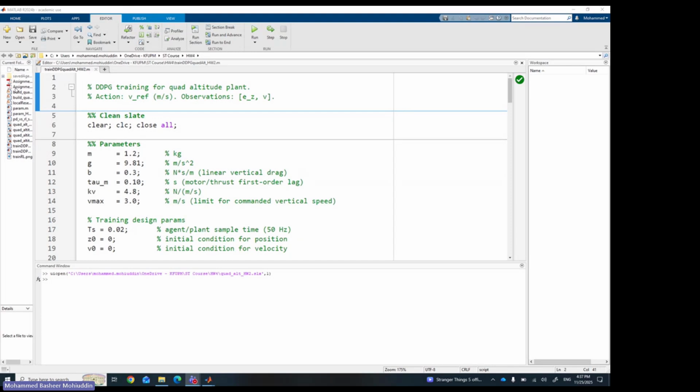It is very important that you have your MATLAB code and Simulink file in that current folder before you run. Second thing, on your right, the positioning may vary based on how you customize your MATLAB, but this is the default setting in MATLAB.